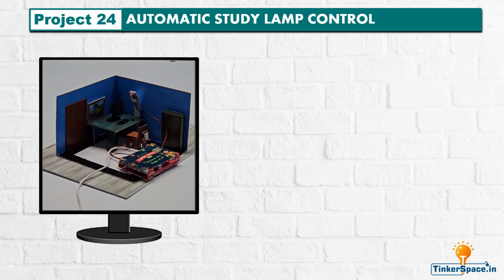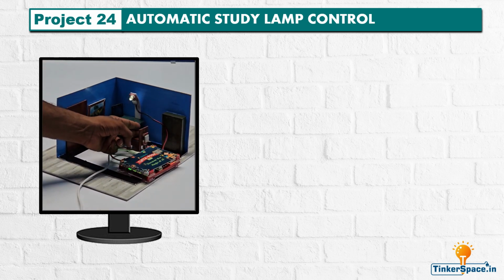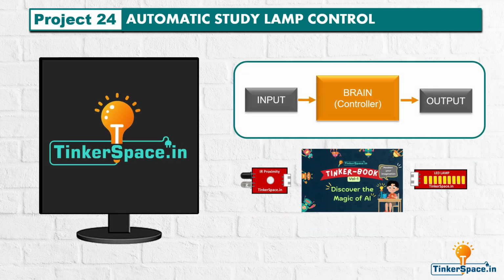Automatic study lamp control. This project creates a study lamp that turns on automatically when someone approaches. In this project, we used TinkerBook Volume 1 as the controller. The IR proximity sensor is used as the input. Its function is to detect the presence of a person. The LED lamp is used as the output. Its function is to turn on when someone is nearby and turn off when they leave.